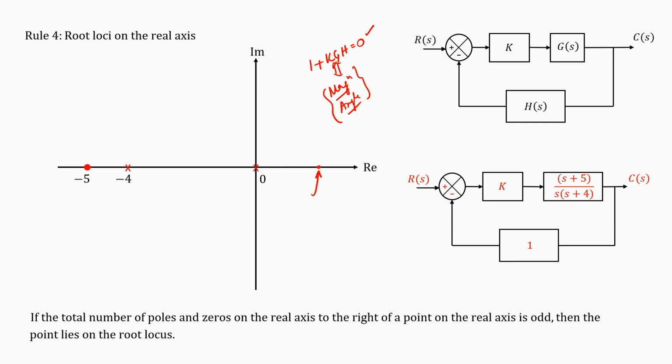In the last class itself, I said that the angle criteria is the most important one, because if the angle criteria is not satisfied, even if you get the value of k, it does not make sense. It will not help you, okay, because the value of k can be found at any point on the complex plane, but the angle criteria is not satisfied by every point. So, now I will check whether the angle criteria is satisfied at this point. We know how to check the angle criteria. For this example, these are the pole locations.